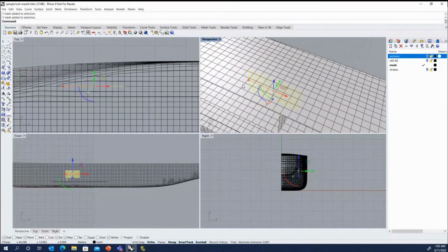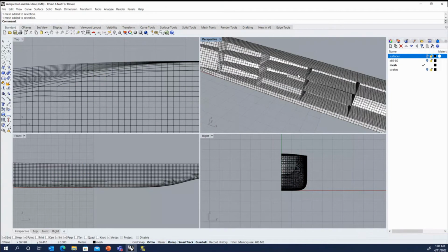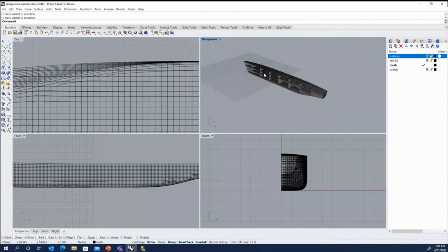The spacing changes from 1 meter increments to 4 evenly spaced increments, getting out to 8.375, and then 2 at 0.8125, and then back to 1 meter increments. So since we're not using that for our stiffener spacing on here, we'll stick with 1 meters, and we'll just accommodate that one bulkhead that's at an odd spacing. So it'll be a little different than the mesh that you see in the sample file here.